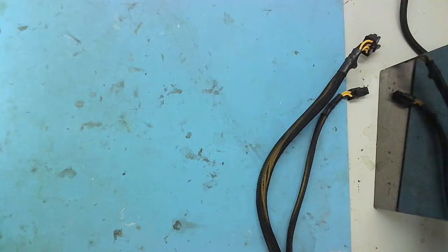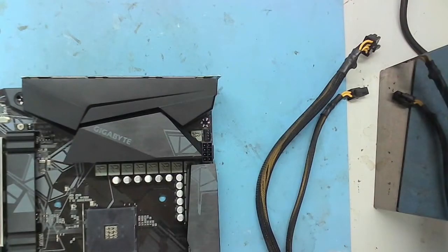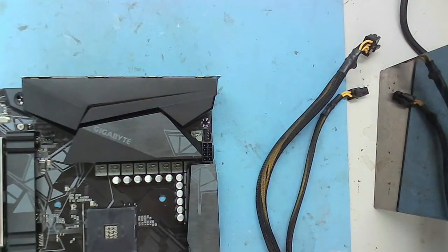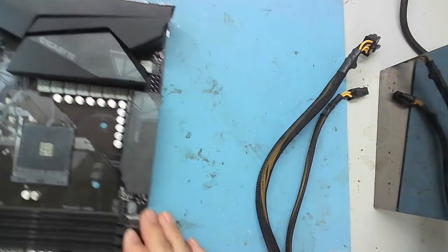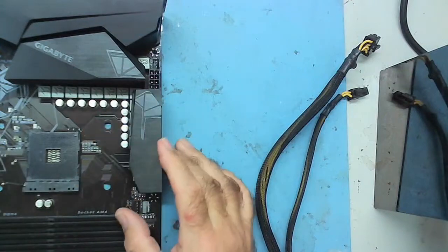I've never seen a north bridge on standby less than 1.8 personally, although I suspect I might see them around 1.1, because I've seen supply rails on north bridges when they're running at 1.1. But I have to say, I've never seen a supply rail on the north bridge any less than 1 volt or 1.1, even on the working board of different chipsets. And that's why.